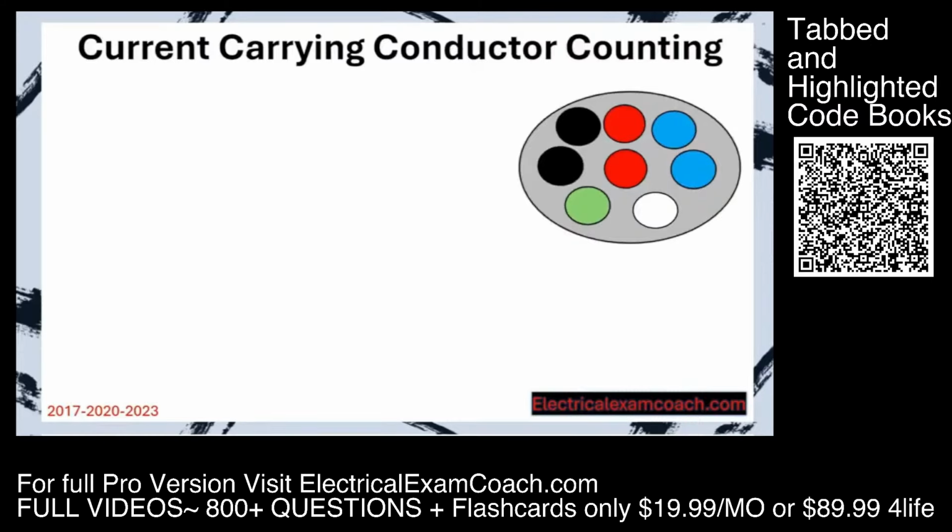Now let's learn about current carrying conductor counting, because we're only going to be counting the current carrying conductors. You may get a question on your exam that gives you the number of conductors. That's easy. You're going to go to the tables and do the math. But you may get a question on your exam that asks you, in a scenario of wires, how many of them are current carrying conductors?